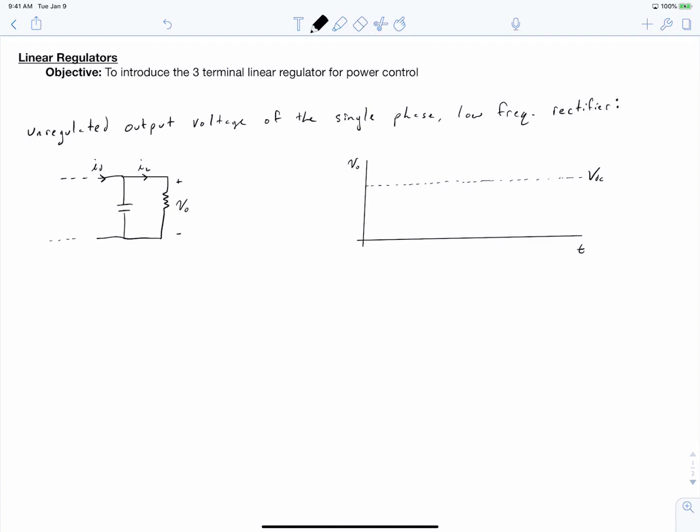And we've seen as we've developed this circuit that that is not true. In fact, our output voltage will fluctuate as our capacitor charges and discharges, and may look something like this. Now, these fluctuations can cause problems for digital circuits. So a waveform that has this pattern, where our output fluctuation is sizable, is really not very useful to us